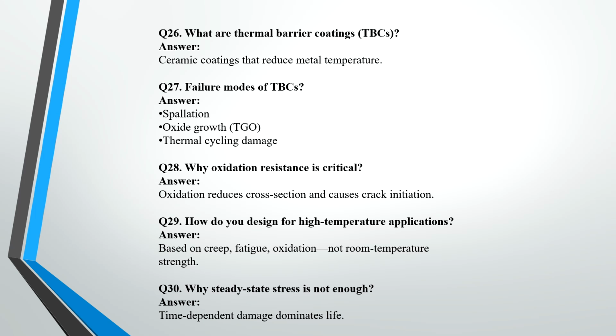Why is oxidation resistance critical? Oxidation reduces cross section and causes crack initiation. How do you design for high temperature application based on creep, fatigue, oxidation? Not the room temperature strength. We are talking about very high temperature. So all this data is used for the designs.